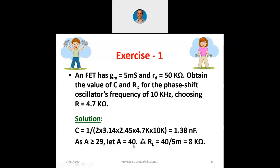When I choose A to be 40, I can calculate that RL is 40 by 5 millisiemens. See, gm is 5 millisiemens. So RL, that load resistance, which is a parallel combination of drain resistance and the internal resistance, is 40 by 5 millisiemens, that is 8 kilo ohms.